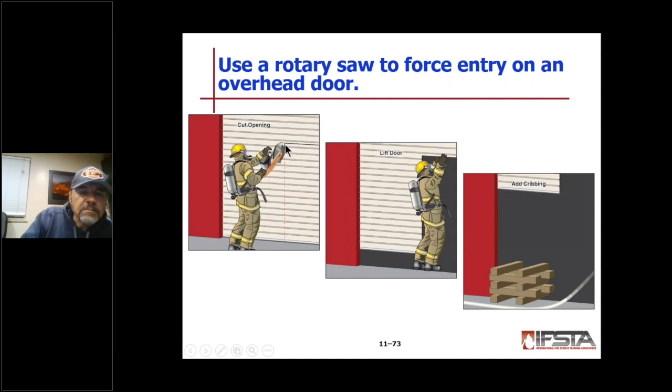Another option is, depending on the door design, you can make this top cut, make a cut down the center or 2/3 of the way through, and then you can pull these slats out. Usually every other or every third slat has a feature that goes into the frame of the door mechanism itself. So these slats are free to slide sideways. A lot of times, if you take enough of these slats out, the door itself will have a counterbalance spring that will open all the way by itself.